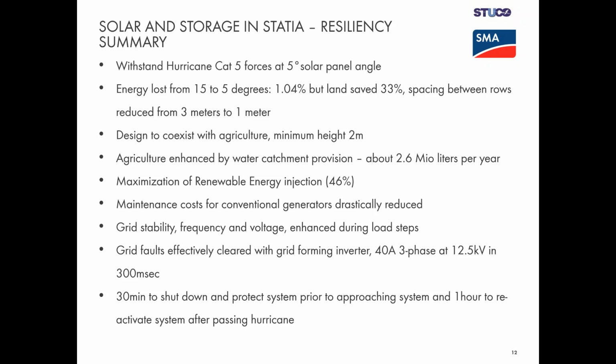And you can imagine the park being able to fully supply the island with power, given any situation at the power plant, be it that a hurricane passed and our power plant is disabled, or a tsunami or whatever. We would then, during daytime, while the power plant is down or being repaired, still be able to supply the island with power once the sun comes up, because we can then black start the solar park and get it up and running and supply power, even though our power plant may be disabled.